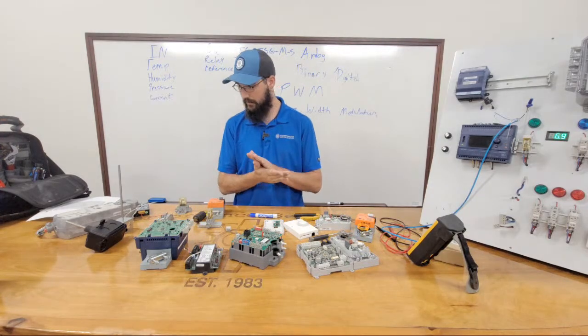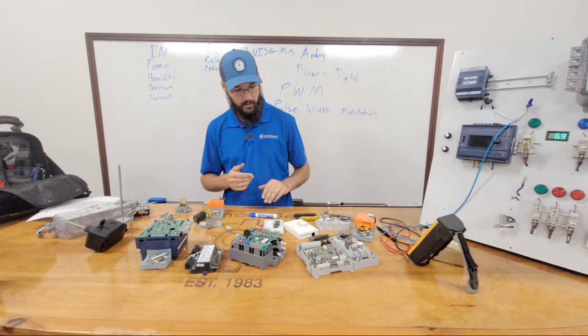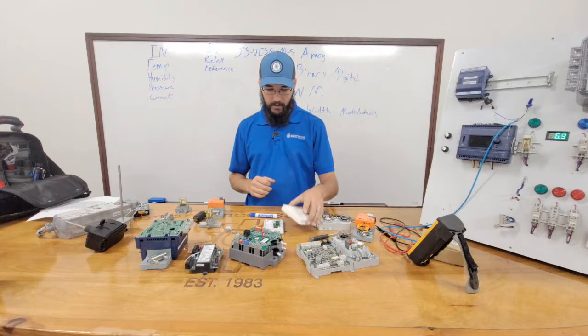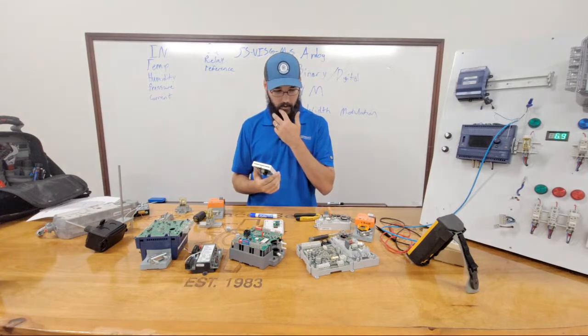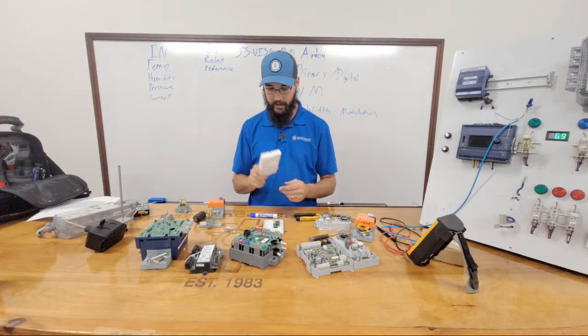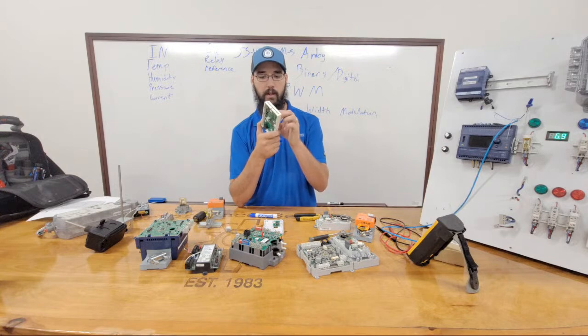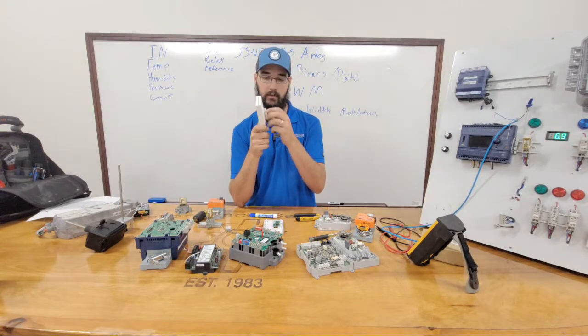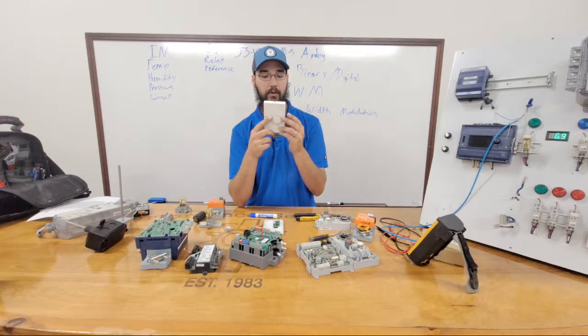Let's talk about temperature real quick. Yeah, I'm watching that. So there's a couple of different ways of controlling space temp. You can have a wall sensor. This one actually has a rheostat, so that's what this little dial here is, and you're able to vary the